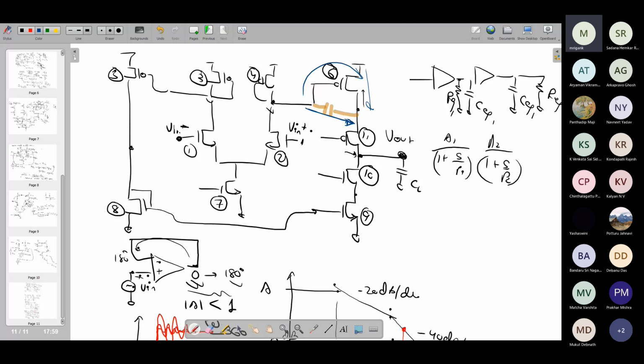In this particular circuit, you don't have that kind of configuration. CGD here is not very high. We will look at some other configurations where we intentionally insert this capacitance to make the circuit more stable, but as a byproduct, it also gives us a zero. So for achieving this stability, with omega P2 much higher than omega P1 and making sure the 180 degree point is exactly at omega P2, we insert this kind of capacitance, which in certain cases will create zeros also.